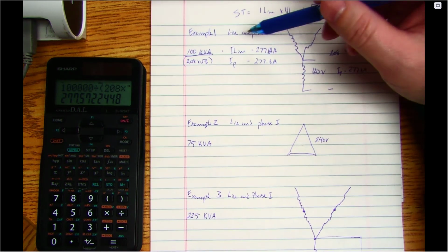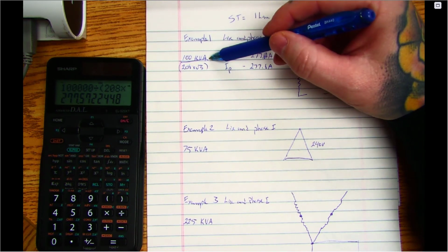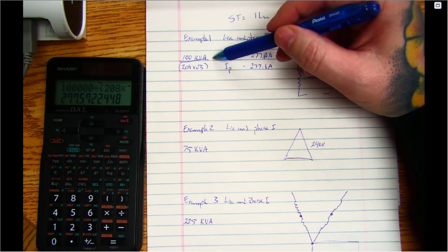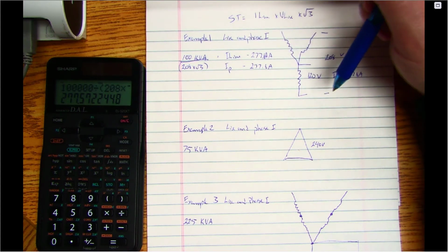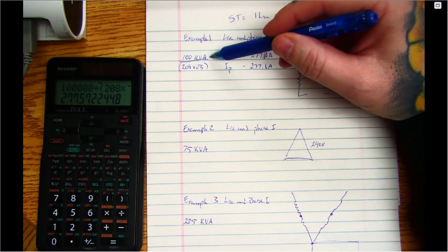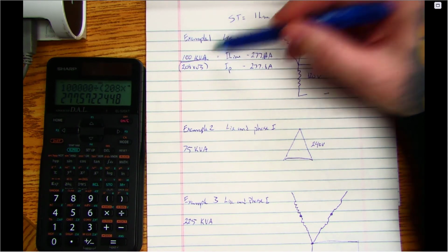That's something that we want to talk about too here. These questions that I'm doing right now, if I'm doing them based on kVA or VA, that's a rated current. That's what the machine is rated to output. Obviously, if we put load on it, that's what dictates the actual amount of current going through it. But just to make sure we have an understanding, if we're using kVA, that's rated current and voltage.